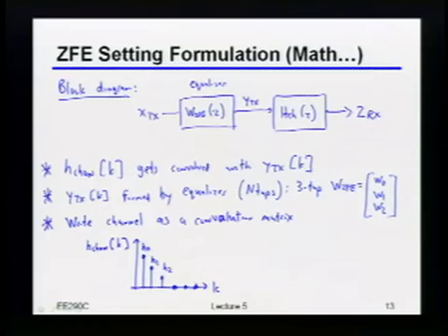Okay? So what I'm going to do is use this to form a matrix that would tell me, if I took this transmitted vector and passed it through the channel, what the output would look like versus time. Okay, so the way to think of this is that this dimension here is implicitly representing sample time. Okay? So I'm just going to call this capital H, channel. And just to give you an idea of what that looks like in this specific example.